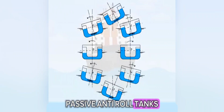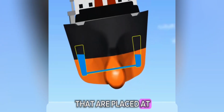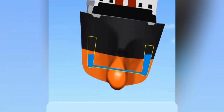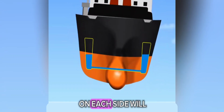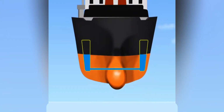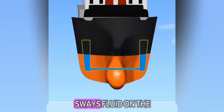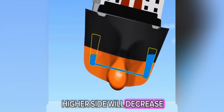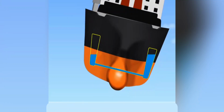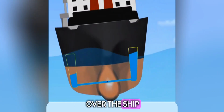Passive anti-roll tanks are another technique used for stability. These are tanks that are placed at the ship's widest points. When the ship is upright, the amount of fluid on each side will be equal. As shown in the animation, as the ship sways, fluid on the lower side will rise and fluid on the higher side will decrease. If one can control the flow of fluid, one can have most of the weight on the lower side as the wave rolls over the ship.